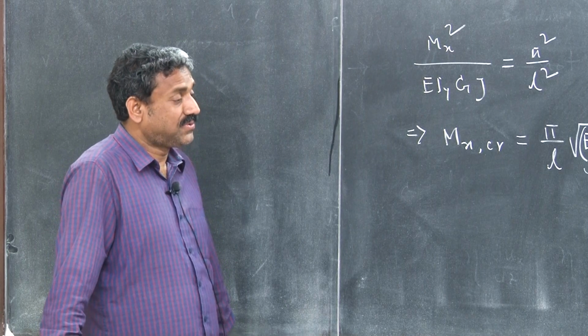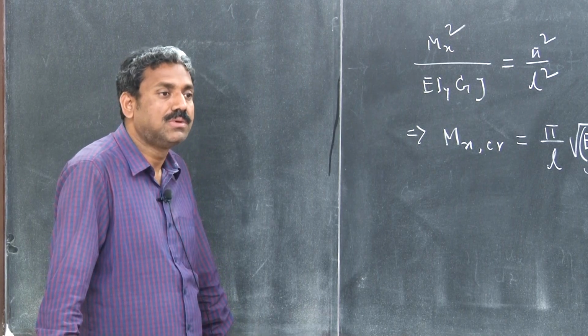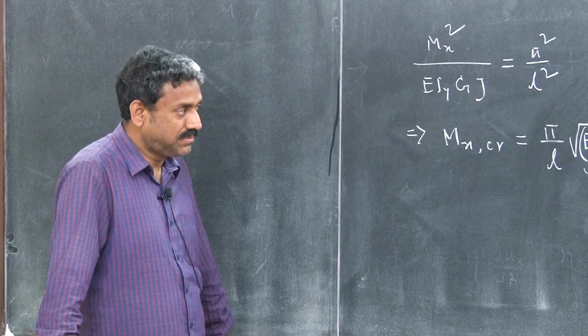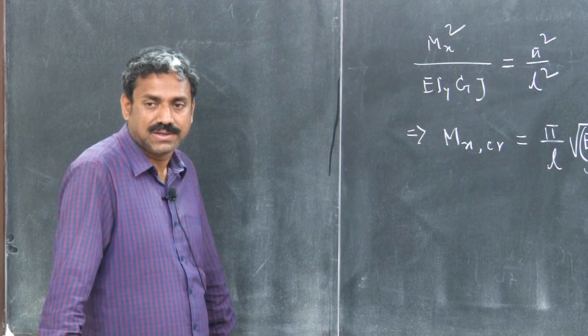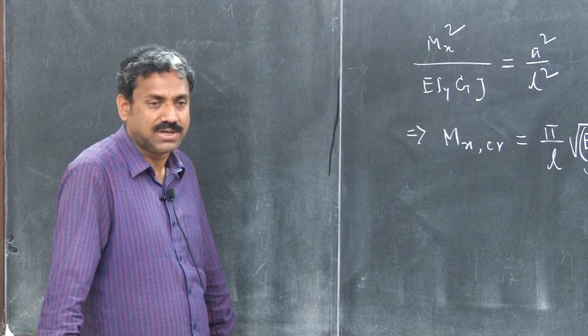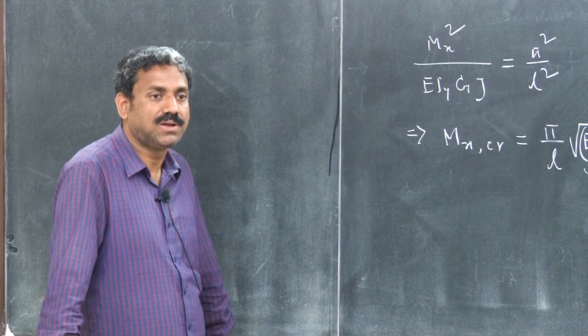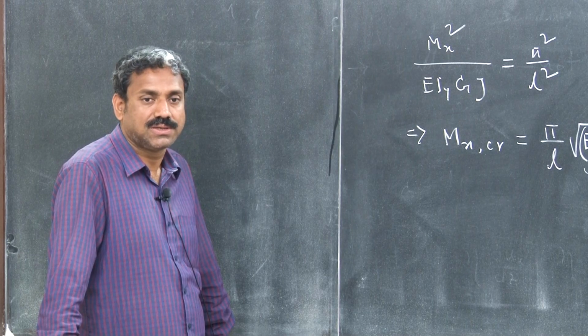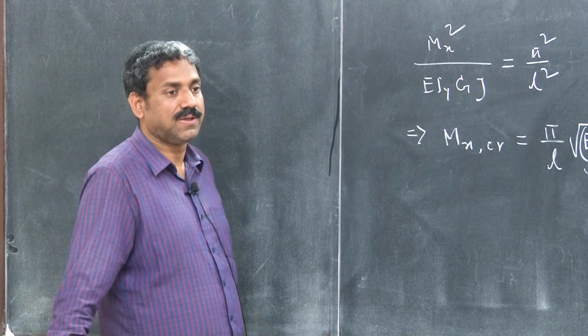And we have seen that for solid section and closed section, because we have very low warping rigidity, the warping is very negligible over there, and we do not need to consider it. For solid section and closed section, in closed section J is what? It is 4A square over the integral of ds by t, those are St. Venant constants, but the warping constant is different.